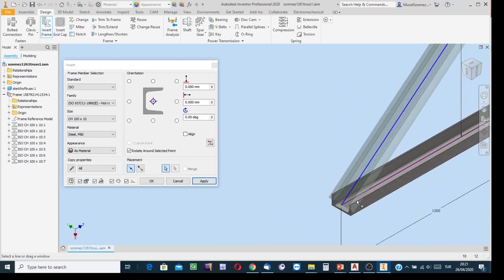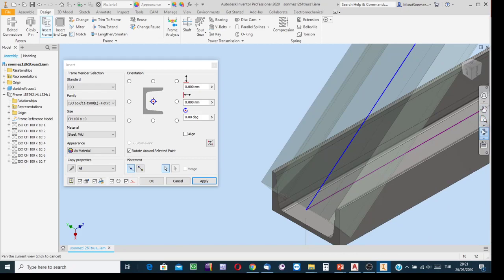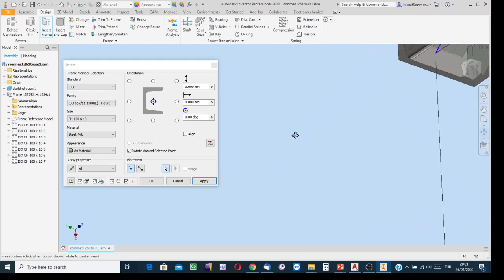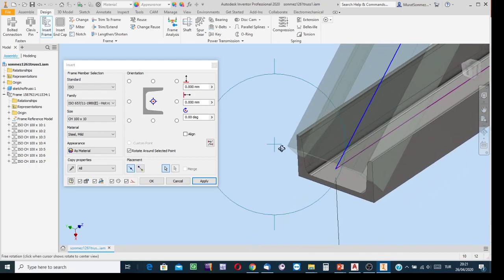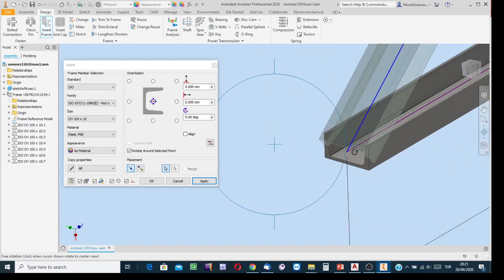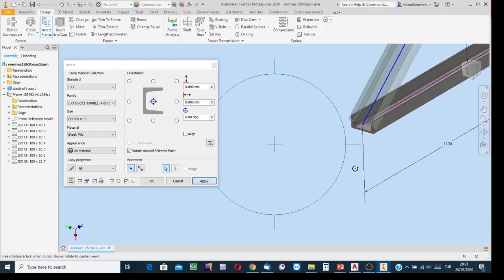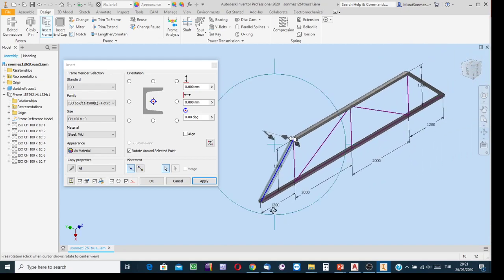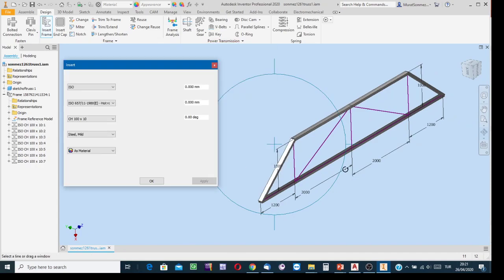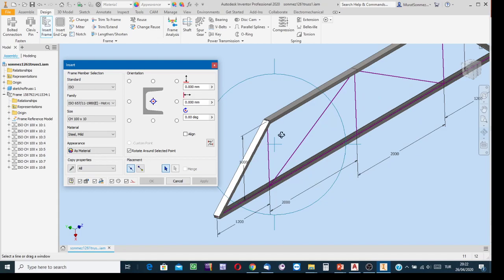And then check whether the legs are in the correct direction. I couldn't understand. I rotated the model a bit. Yes, I see from the simulation the flat surface is toward the outside. So this orientation is correct. Apply. Okay. Yeah, mating. You see, the most valuable part of this facility is mating. Just simply indicating the skeleton, the orientation of the member, not the cross section, with respect to the others at the joint is achieved by the software. Okay, and then continue.